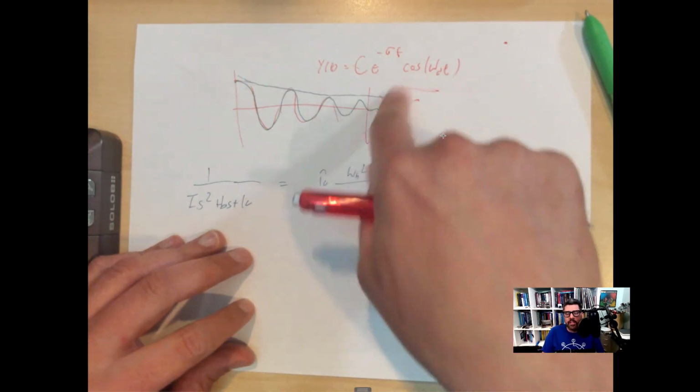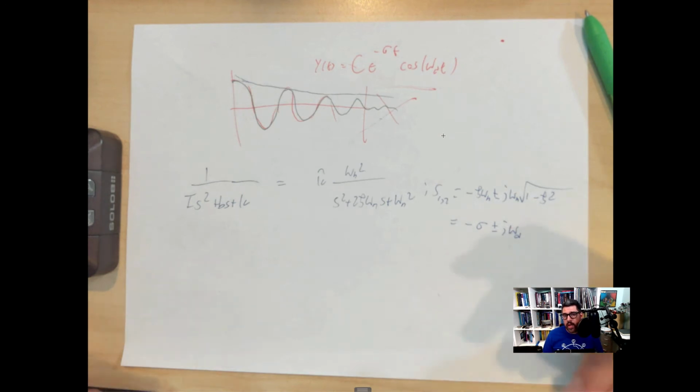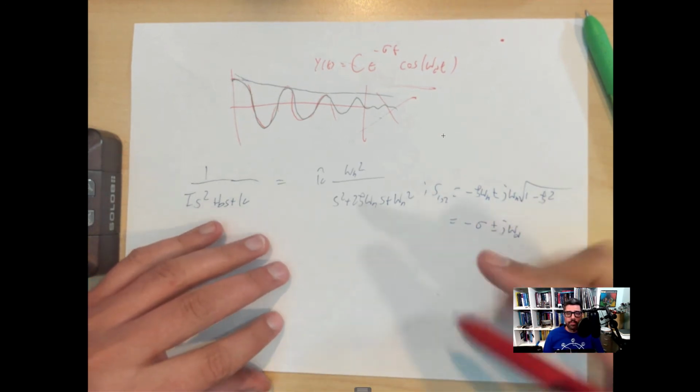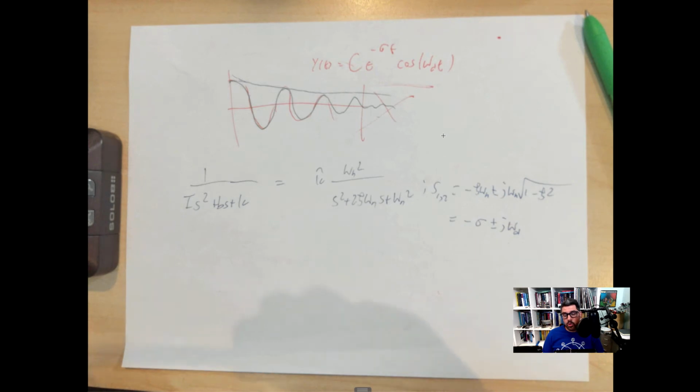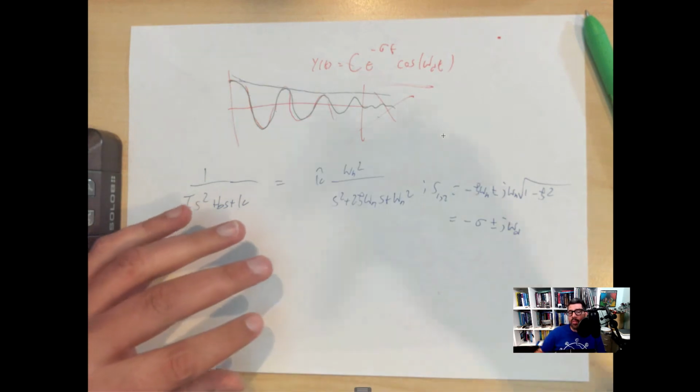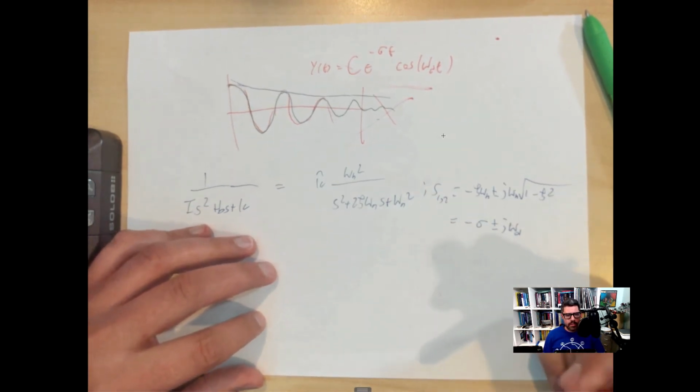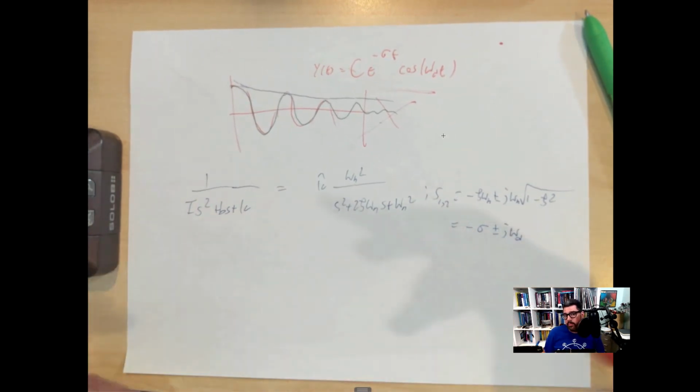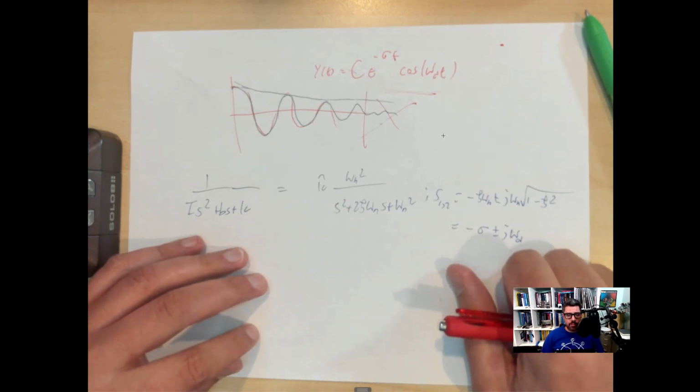And you're going to fit this. Now, how do you fit it? Well, there's a few different ways. I'm going to let you figure it out, okay? But one example is use nlinfit. That's a function in MATLAB. You don't necessarily need to do it that way. But if you were taught that, for example, in data analysis, then you can use that function in MATLAB, okay?